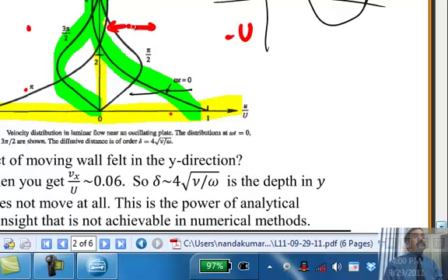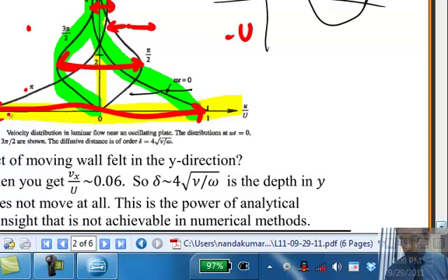So if you take a point from here, for example, it sees very little oscillation. A point here might see a much larger oscillation. The point here, you see an oscillation like this, whereas this is the maximum oscillation that you can have, from -1 to +1, minus u to plus u. Because of the shear stress reversal, the flow reversal itself, it cancels.